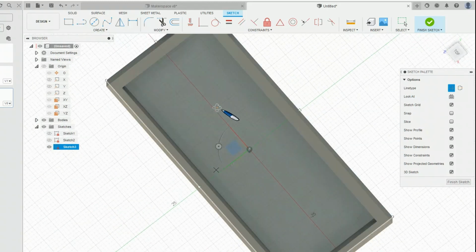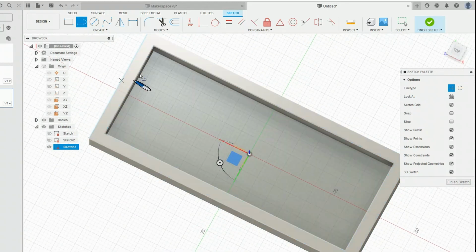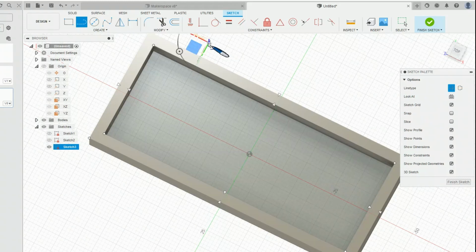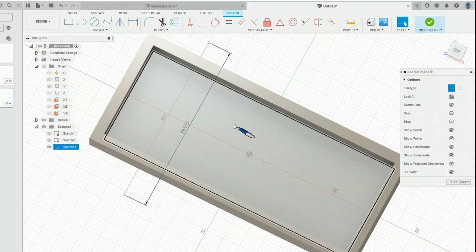So working from that view, what I'm going to do is just draw a line at a random point sort of close to it, and the only thing I want to make sure is, just tab over to it, that the angle is 90 degrees. So where that angle is, I'm just going to type in 90. And the length is not critical so long as it is around the length of the box. We're just going to go for a random at the moment, so I'll hit enter on that.